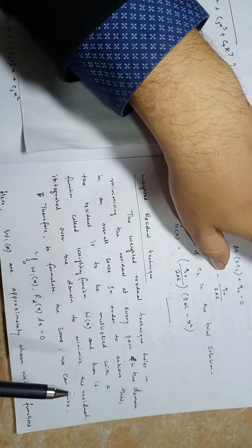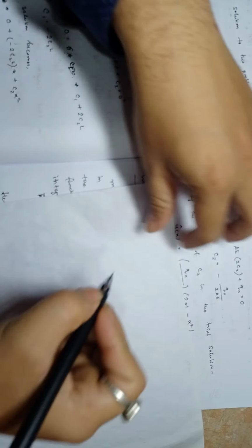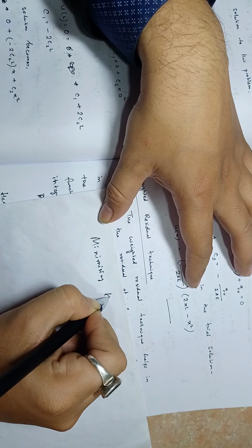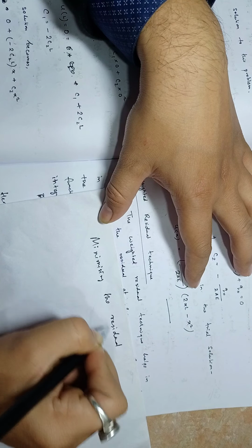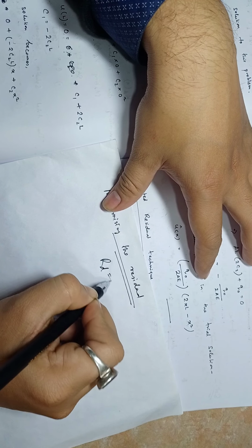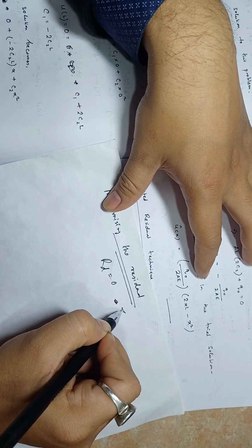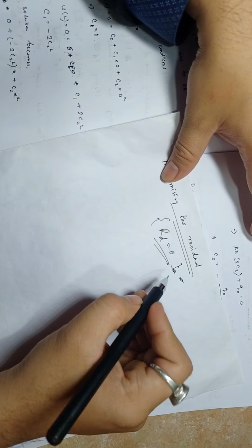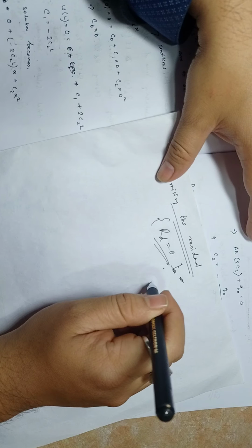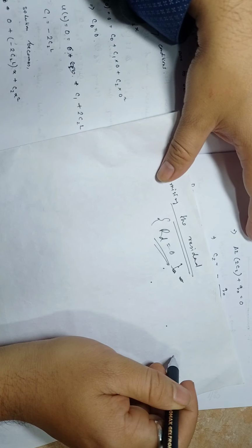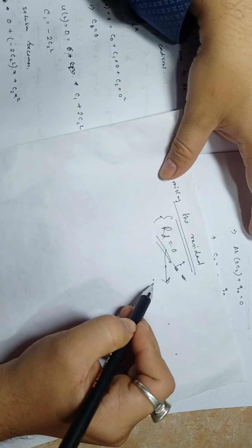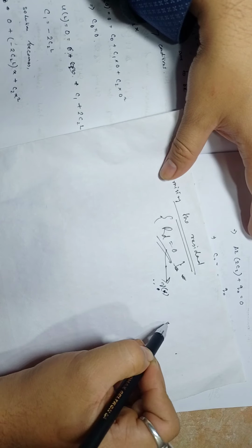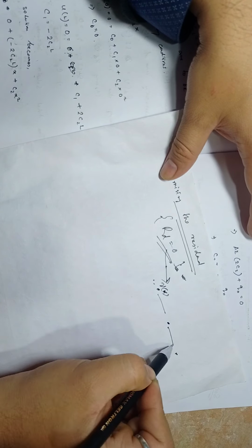So this weighted residual technique is nothing but minimizing the residual. Okay, so till now, minimizing the residual. So when you make RD equal to 0, this may not give you the exact solution every time. Or at one point or another point you can find out the value of that dependent variable, at some points, but it may not be 0 at all the points.